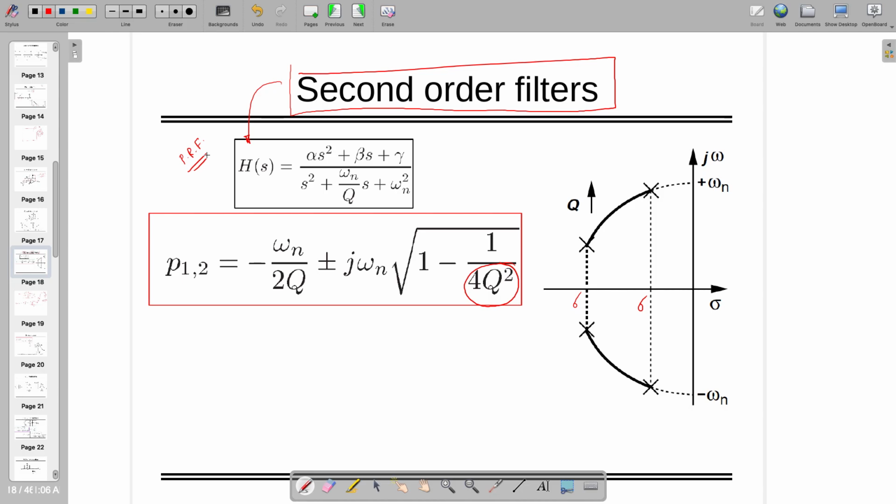Then if you look with the partial fraction method, if they are all coming with negative residues, then it's an RL impedance and RC admittance. If it's giving positive residues, we can find an RC impedance and RL admittance, right? So these are the properties through which you can design second order filters, and that is possible, right?